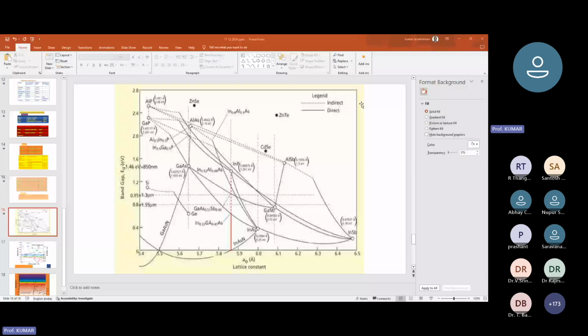Now it's perhaps easy for you to follow that the distance of separation is what is called a forbidden gap, and this forbidden gap defines the band energy, and this band energy is very, very important in understanding any material, either it is a conductor or an insulator or a semiconductor. So if it is a metal, the Fermi energy overlaps, and therefore there is no real gap, whereas in a semiconductor there is a defined gap, whereas in an insulator there is a very large gap, and therefore unless you apply a very large electric field or very high temperature.